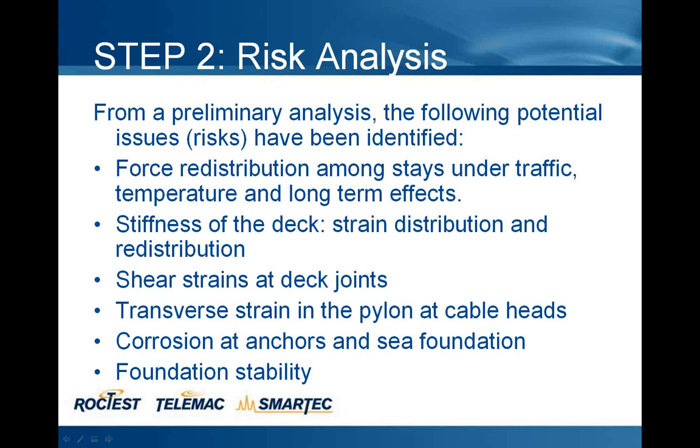The stiffness of the deck, which was considered very stiff, also induces a strain redistribution among the stays, but also within the deck itself. Also, there were some doubts about how the shear strain is transmitted at the deck joints, and also how the strain is transferred from the forward stays to the backward stays in the pylon itself. There are also some risks associated with corrosion, in particular at the foundations that are in the sea and at the anchor points, and finally some doubts about the stability of the foundations themselves.